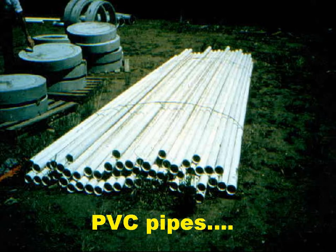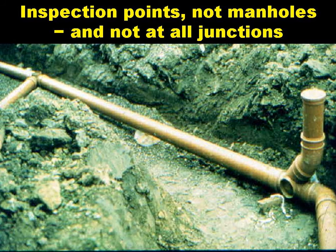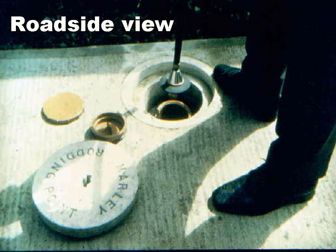PVC pipes are now very commonly used, simply because they're easy to lay and joint. And instead of expensive manholes, we use very simple inspection points, and we don't have to have an inspection point at every junction between one sewer and another. So costs are reduced. And this slide shows the roadside view of the top of an inspection point, where access is available to the sewer for rodding out blockages.